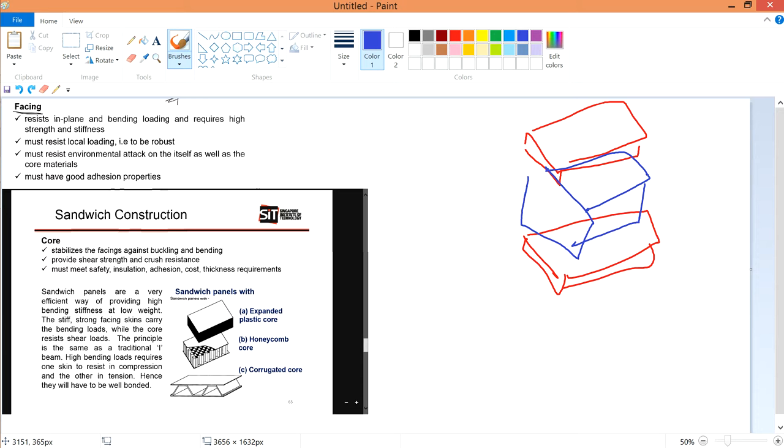It helps to support the bending, because you increase the height of your material, so it helps in supporting the bending issues. Also, because you make the overall thickness of your material kind of thick, when certain forces act on it, it will not buckle. Buckling, if you forgot, is like this. If you were to buckle, you'd move something until like this. So buckling is similar to a bending type of thing. Therefore the core itself acts as a support to prevent buckling and bending from occurring.